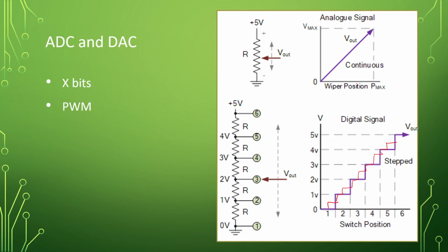The other thing I have up on here is PWM, so digital to analog conversion. That's taking it the opposite way. Oftentimes when we are changing the value of something, we're actually pulsing it in the world of DC. So it's how fast you are turning that signal on and off, basically. I've got 10 volts and I've got 0 volts. If I need a 10-volt signal, I would just send 10 volts. It's really easy. If I need 5 volts, though, how do I do that? How do I send 10 volts out but only get 5 volts of actual?